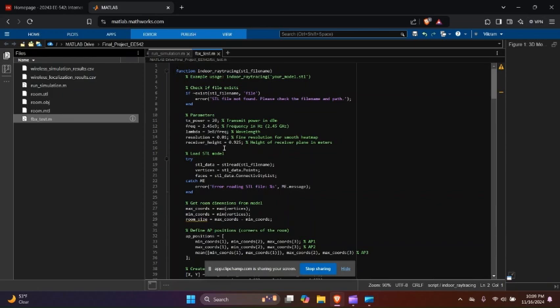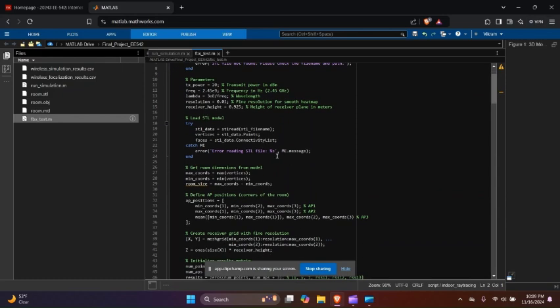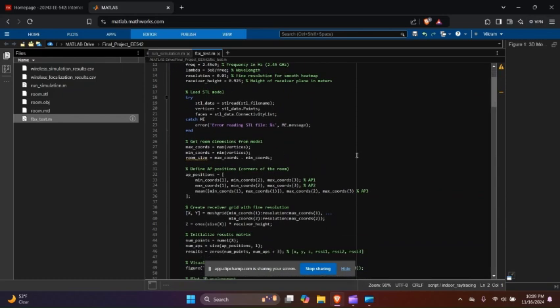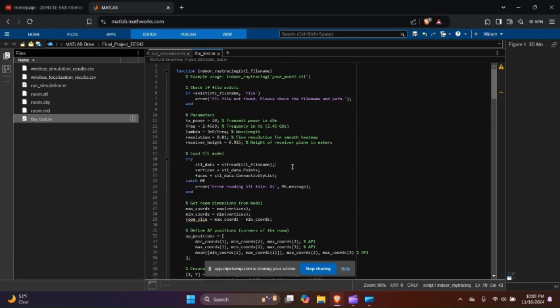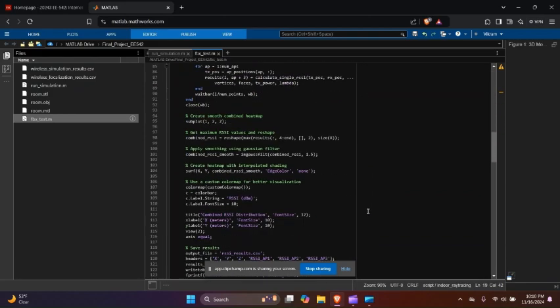And this is one such step in this video that we are showing, which is we have ray traced a 3D model. Sarvesh has done this using Blender, and here I'm importing that Blender model, and then applying path loss to this model, and then calculating the RSSI values. So it's essentially simulating measurement from a real room, right? I will walk you through it. I'll actually show this code to you. So this is what I did.